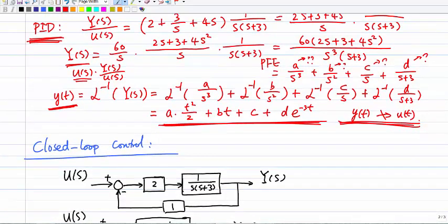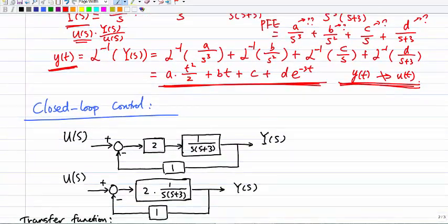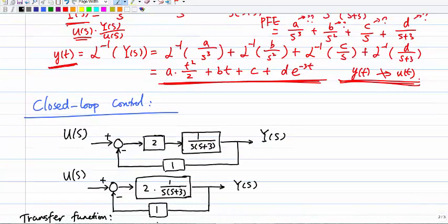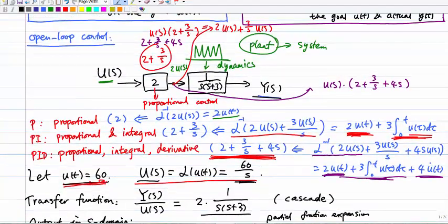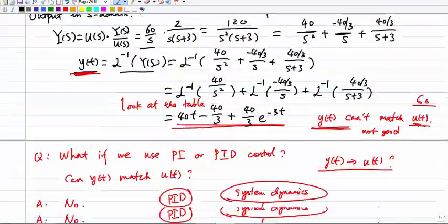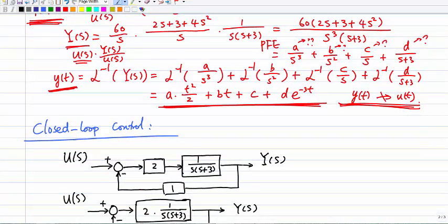Alright, now let's take a look at what a closed loop control is. The closed loop control introduces the only difference here. Compared with the previous one, which is an open loop, the closed loop has a sort of feedback. I'm going to use my actual reading, the moisture level, and feed it back, comparing the difference between the desired moisture level and the actual moisture level.